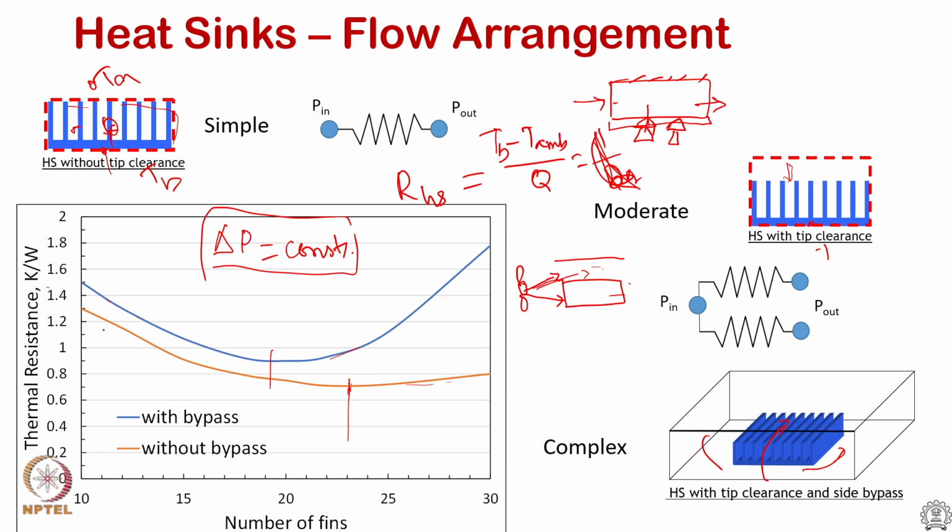So, you can see that as I add more surface area, resistance is dropping, but notice that I do not have a graph here, but the mass flow rate will drop, because my surface area increase will concomitantly increase the pressure generating force, that is, the mass flow rate will go down, because the pressure generating force is constant, or the pressure drop is constant. So, eventually it comes to a point where the surface area is high enough to dissipate a lot of heat, that is the resistance, because the Q is increasing here, and the resistance is dropping because my T base is fixed to a constant, T ambient is fixed, only this is increasing as I increase more fins here.